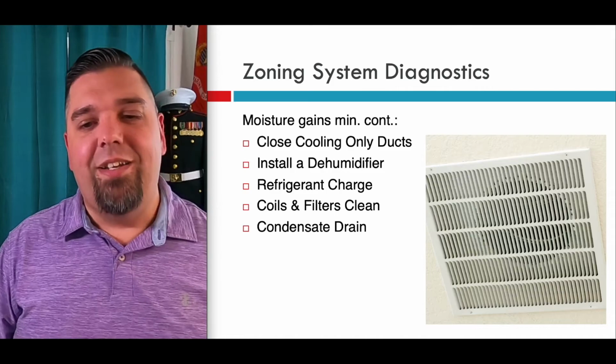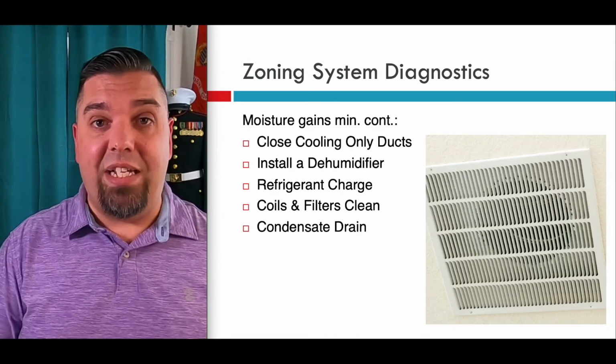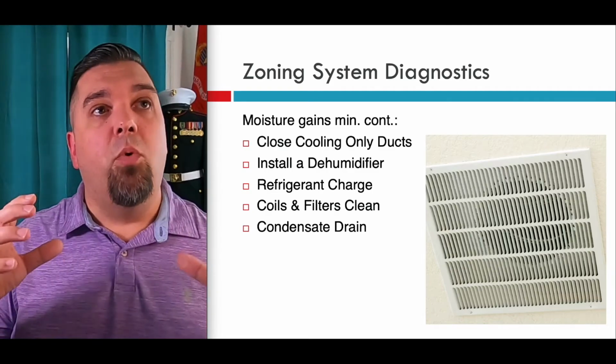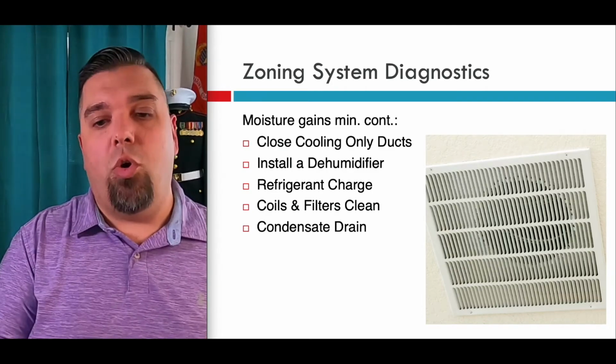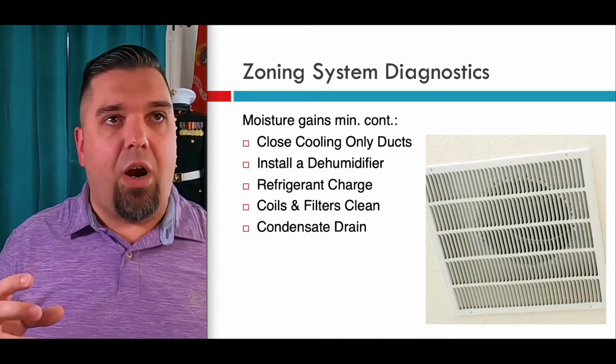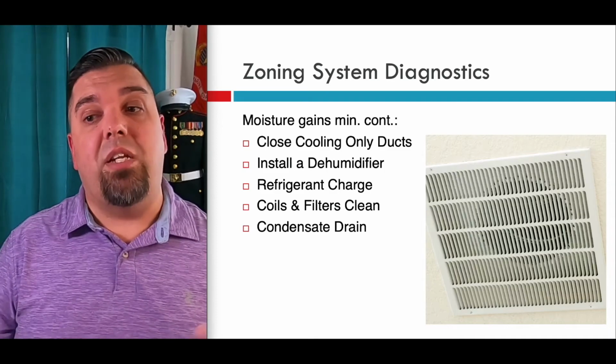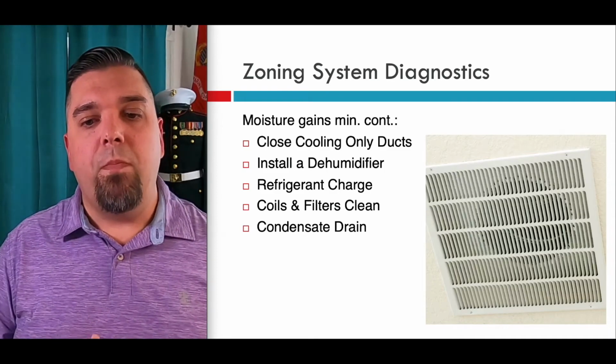and then close it in the winter, right? Another way to control that moisture is obviously installing a dehumidifier if you have a moisture issue in just one part of your home, right? But keep in mind, dehumidifiers, because you're moving air out, if you're not venting it to outside, you actually will heat the space and it's going to fight your air conditioner, okay?